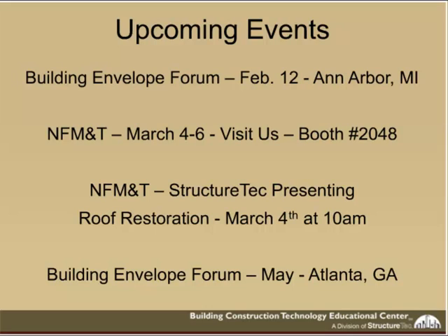Here's a good one. We have Randy from Minnesota. Randy's wondering, I have stair-step cracking in a few different areas in my facility. Is that a sign of structural problems? It's a sign of structural movement, which may or may not be a problem. What's important is to make sure that that movement is being accommodated properly by joints and systems. So not necessarily a structural failure at this point? Right, it's not a structural failure. If you don't provide a joint, the building will make its own.